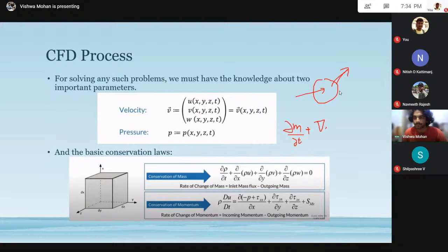So the divergence of something like somewhere where the mass is coming in will be negative, and for something which is going out of the given volume, it will be positive. So you use this operator of divergence on rho and velocity. Why rho? Because as I told you, this mass is not mass, this is actually rho, as the whole equation is written in terms of mass of that small control volume, but it's divided by volume. So the whole equations that you get here are in terms of rho. So this is so simple.